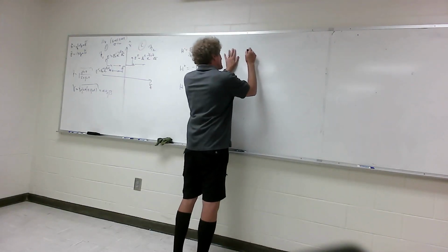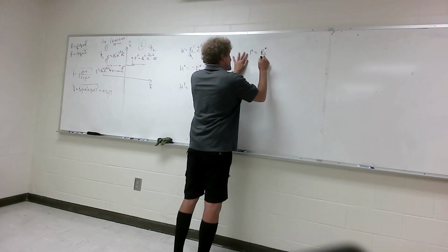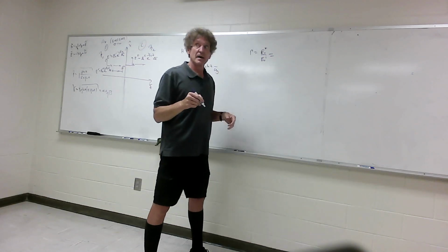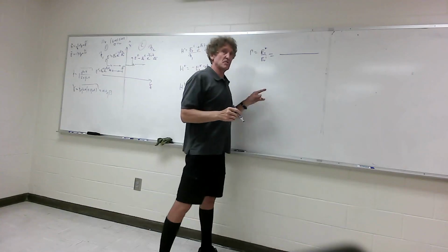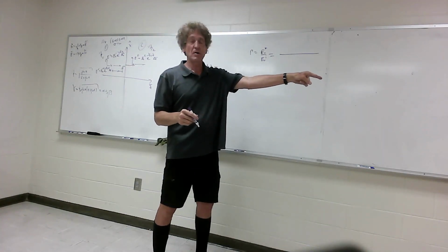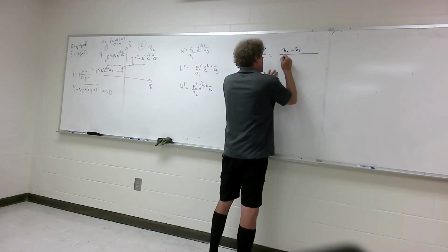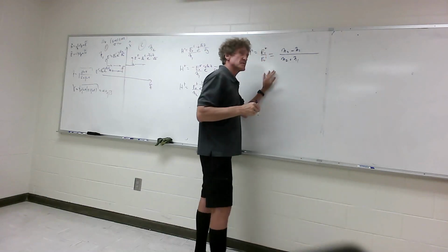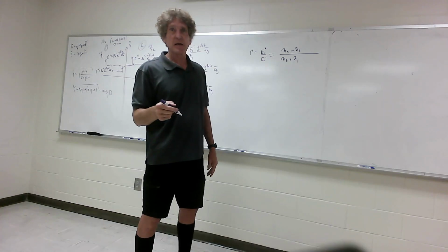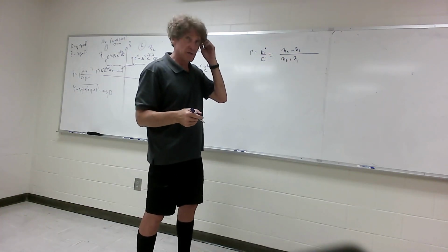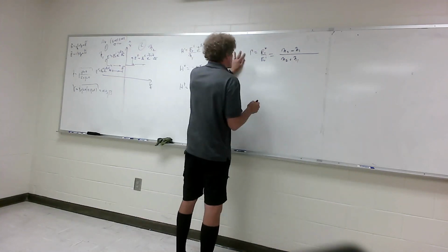So when we take a look at the reflection coefficient, that's the ratio of E naught reflected to E naught incident. How many remember that? You're going to need to know this. What is the secret? Like I always say, it's always the impedance you're going into minus the impedance you came from. So it'd be eta 2 minus eta 1 over eta 2 plus eta 1. It's very similar to the reflection coefficient on transmission lines. It's always the characteristic impedance of the load minus the characteristic impedance of the transmission line over the sum of the two. That's the reflection coefficient. This is for normal incidence.